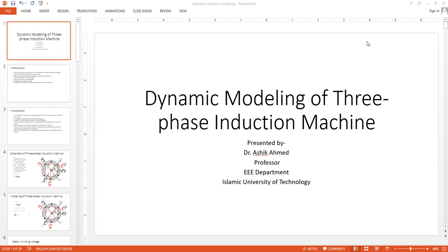So today we will continue our modeling part, but now we will be more focused on the load end. If we consider the load scenario for a power system, we can distinguish different kinds of loads based on their characteristics. For example, in most of the industrial loads, as we all know, the loads are induction machines. That means in most cases, these are dynamic loads.